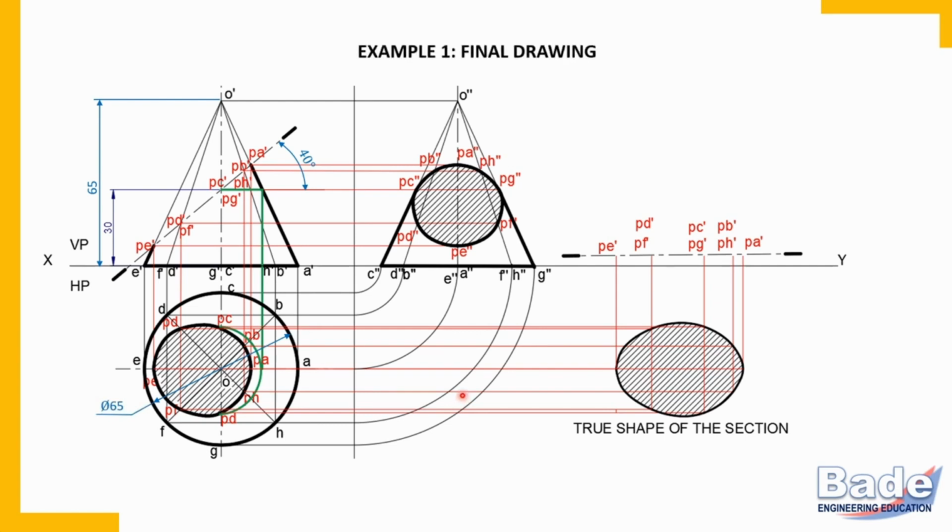This is final drawing. Remember, all given dimensions, that is height of the cone, length of axis, diameter of base of the cone, location of cutting plane, 30 mm above the base, inclination of cutting plane, all these given dimensions you must insert in the drawing.